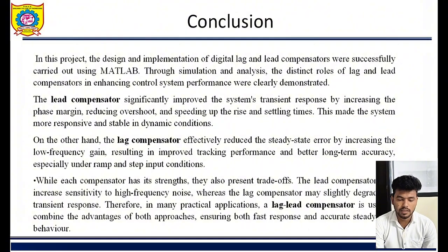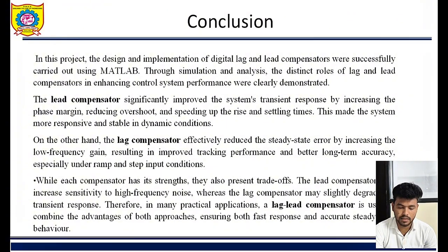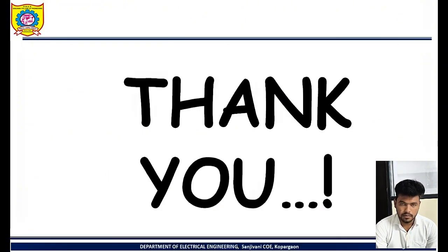The lead compensator significantly improved the system's transient response by increasing the phase margin, reducing overshoot and speeding up the rise and settling time. This made the system more responsive and stable in dynamic conditions. While each compensator has its strengths, they also present trade-offs. The lead compensator may increase sensitivity to high frequency noise.